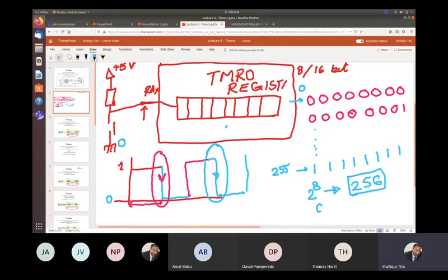The main component of the timer is a register. There is one register dedicated to a timer. The register is nothing but a memory location, and this is a register that we have inside our microcontroller. For any register, the content can be changed by an external clock pulse or external signal. Any kind of external signal can change the content. Normally it is an up counter or a down counter, and this timer is an up counter. So this register is an up counter register.